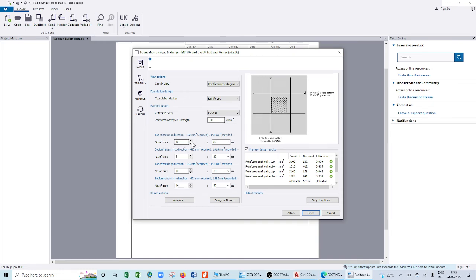Then the iron bars. So you can go here, you see numbers of iron bars. Now when you're reducing the numbers of iron bars, it will be reducing on the spacings. So me, if I'm using, let's say maybe just 6, on the X. Now when you look at this, it's showing you on the top. But when you look at the bar size, it's showing 20. So you can adjust that. Instead of using 20, go back to T12.